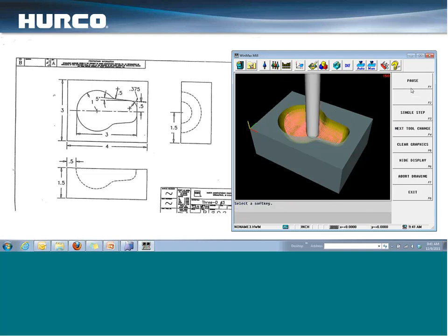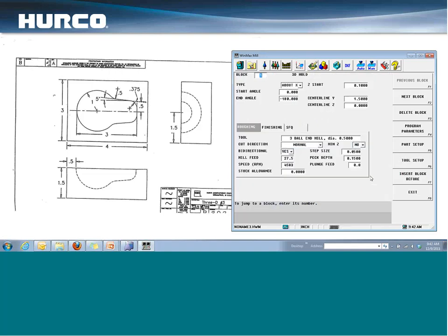That's what I was wondering about, on the edges, if you're only going 10 thou on the first pass. It's getting a smaller pass. You'll be barely touching this little bit of the bottom until you get down there to clear all that out. It would make you double the time.